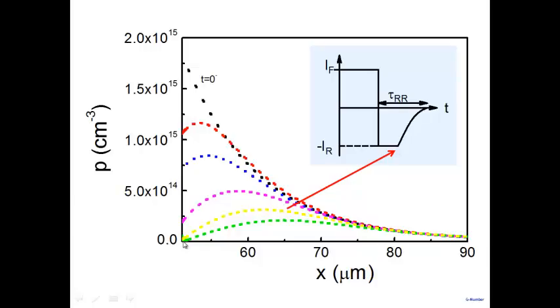The moment it drops to almost zero here, this part is controlled by a diffusive process. This end, when it drops to zero, is this particular point. After that, all this part that you see here is coming from all this charge that you see here. Now it slowly recombines and some of it keeps on flowing there. But diode voltage has no effect now. It's not controlled by diode voltage anymore. It's controlled by how this particular charge is diffusing towards the right, and diffusion and recombination decide this particular part.